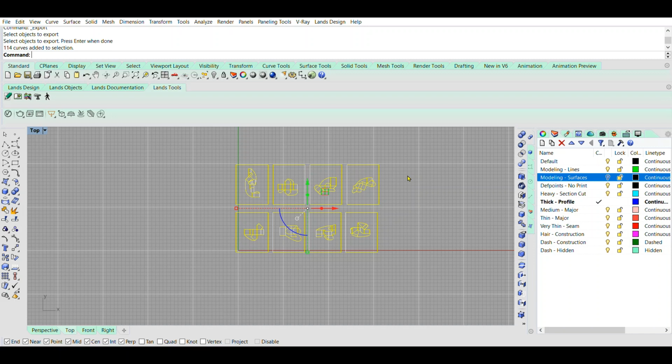For this example, we're going to export in the DXF. It's also called the AutoCAD DXF file format. So we're going to go to File. You're going to select everything that you want to export. File, Export Selected, and then you'll choose wherever you want to export that. And then you'll want to choose that file type, AutoCAD Drawing Exchange, it's the .dxf.